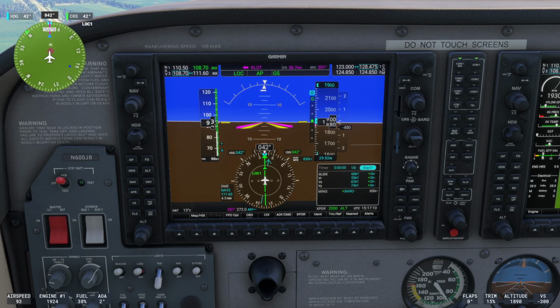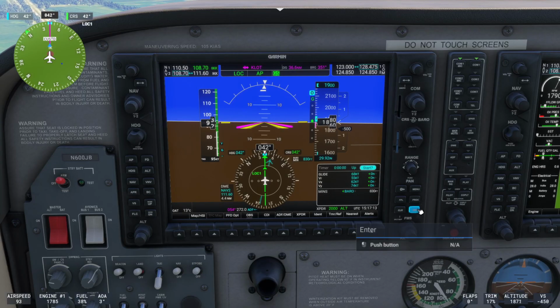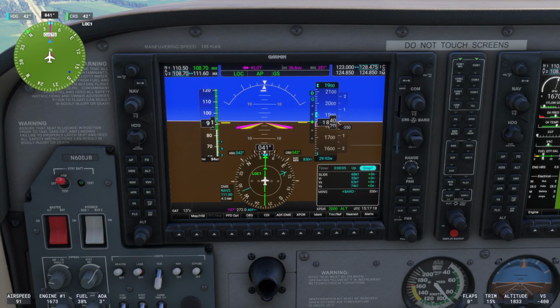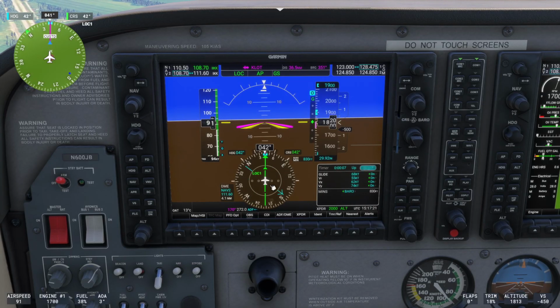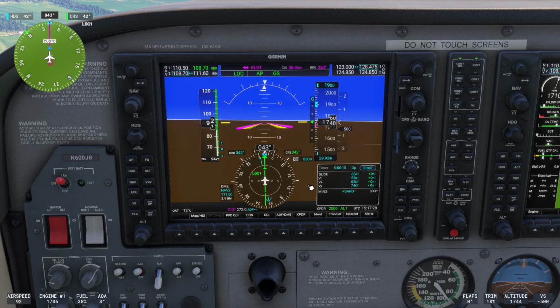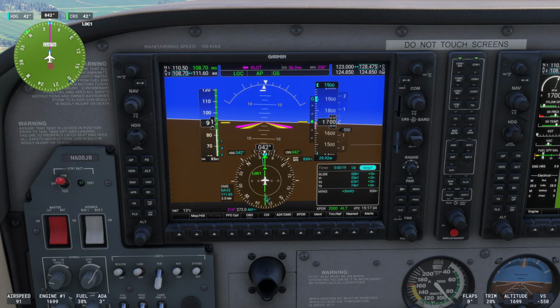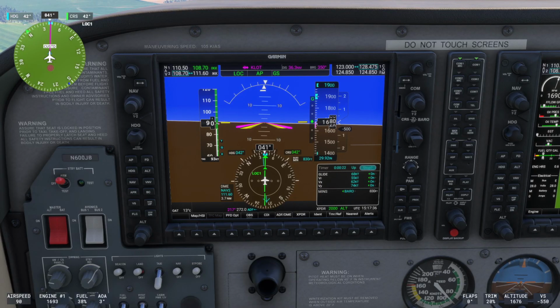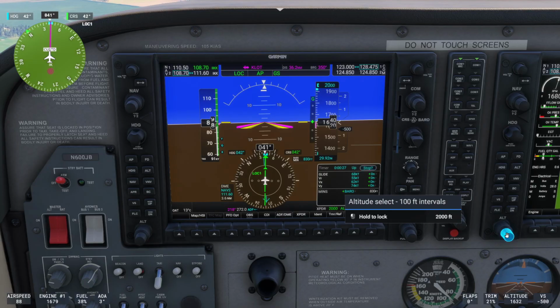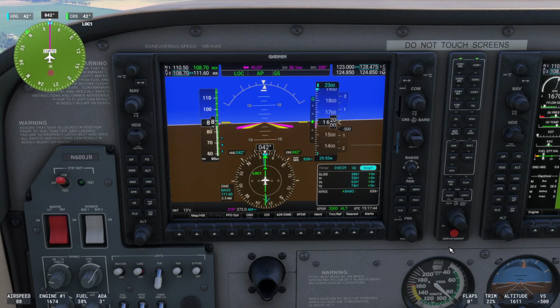All right, so approaching this 4.4 DME from the IKK DME station. That's how we know we're at our final approach fix. So I'm going to go ahead and start our timer. And we can also see this RMI needle start to flip around, as well as the outer marker indication start to blink and give some beeping noise. So like I said, that's how you know we've passed a station when using ADF, is we see that RMI needle flip around. So the compass locator was in front of us, and now it's behind us. That needle flipped 180 degrees. We've passed the station, so to speak. So we're just going to continue the approach down to minimums, and then we'll go missed and see how that looks.